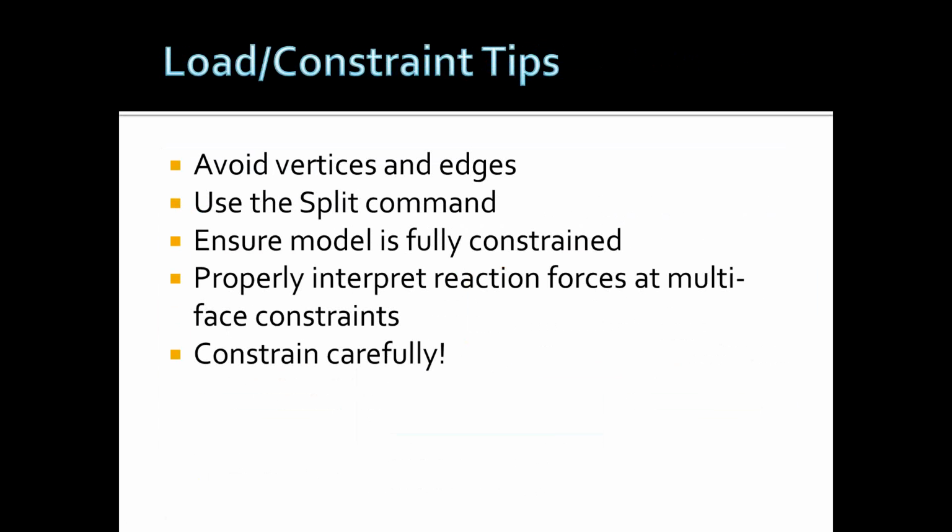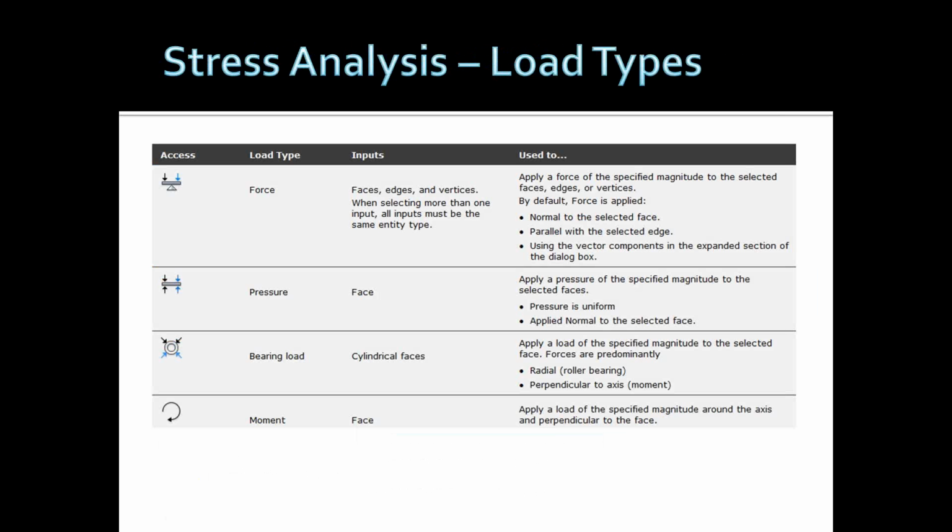You want to make sure your model is fully constrained. You don't want parts that can move and go all over the place. You want to really look at your reaction forces, and you want to constrain carefully. You can constrain it in such a way that the simulation will not work because it can't apply the force, or it looks like it's going to pass all your tests and really it could fail. So you want to watch out for things like that.